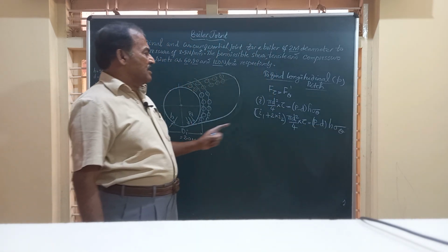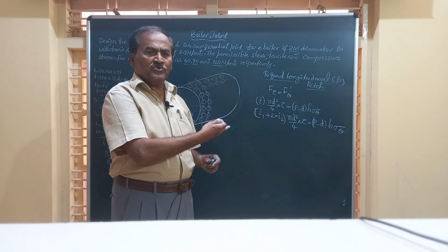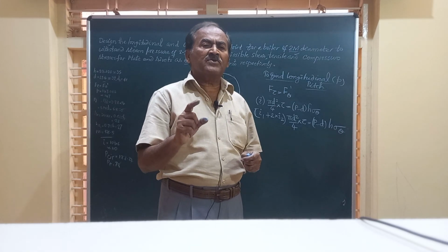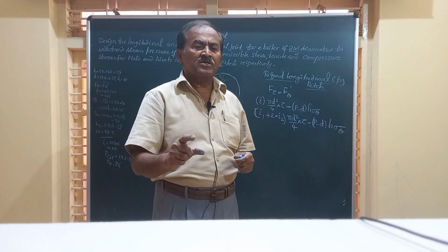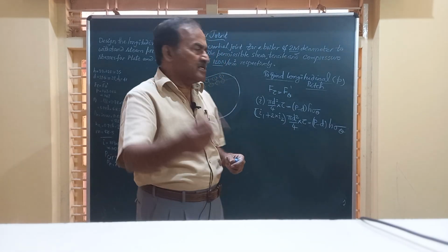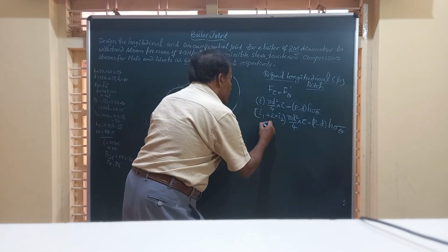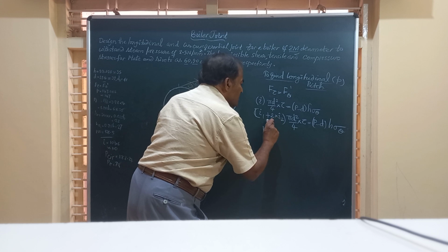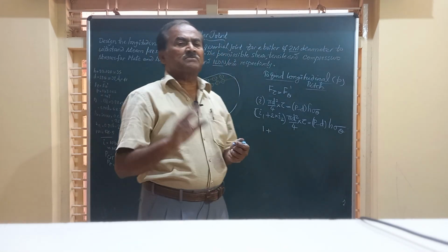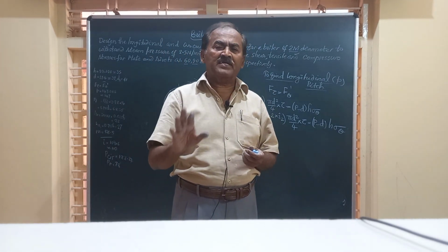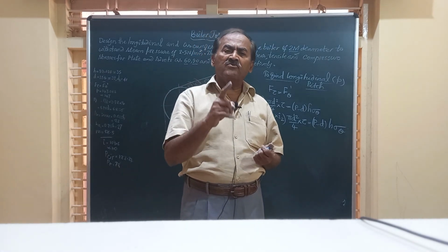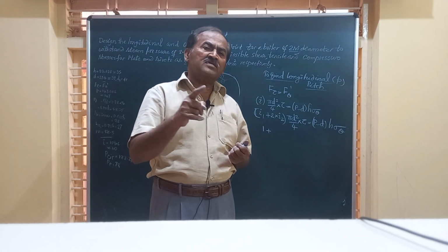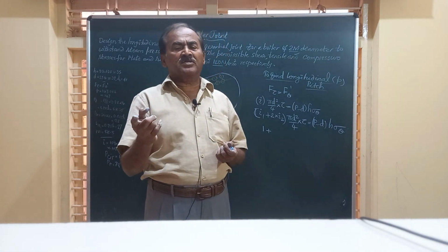Here I1, I have shown you in the previous step, stands for the number of rivets failing by single shear. The first row fails by single shear and I1 is equal to 1. Now, instead of 2, what happens? It has been found by practice that a rivet failing by double shear is not twice as strong as a rivet failing by single shear.